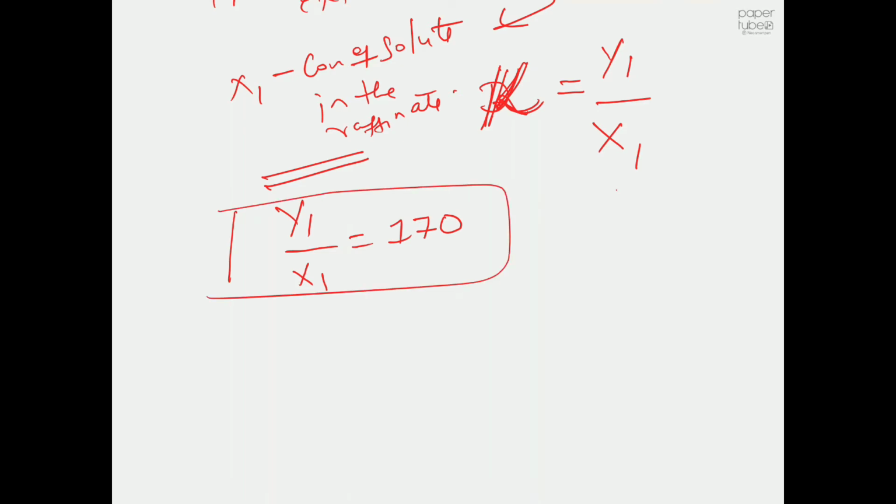So before, we were used to using the ternary diagram. From the ternary diagram we know how to take one point, and then from there we can calculate the fraction of solute on the raffinate side and the fraction of solute on the extract side based on the tie lines. But here we made the problem much simpler using one terminology called the distribution coefficient. So if we know the solute concentration on the extract side, then we can calculate the solute concentration on the raffinate side using this simple relationship. I hope you all follow up to this point.